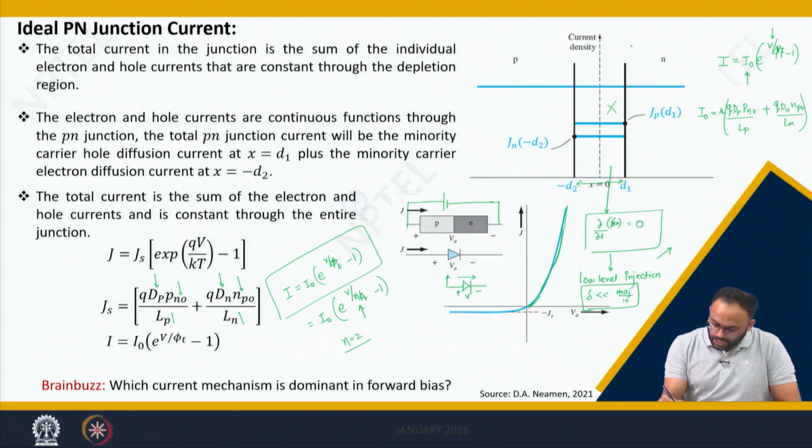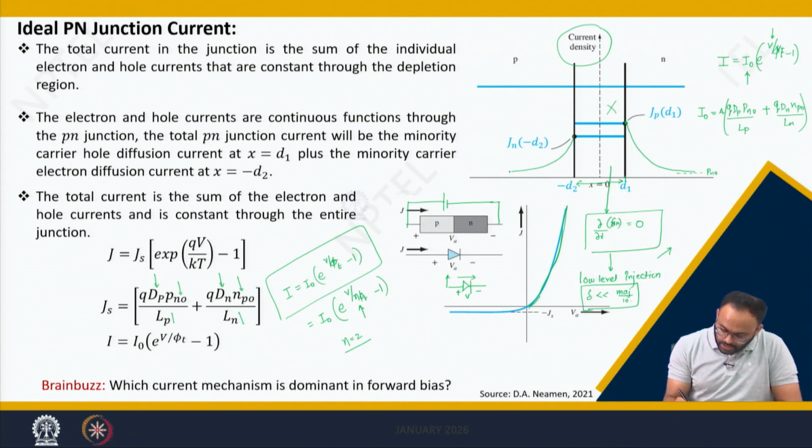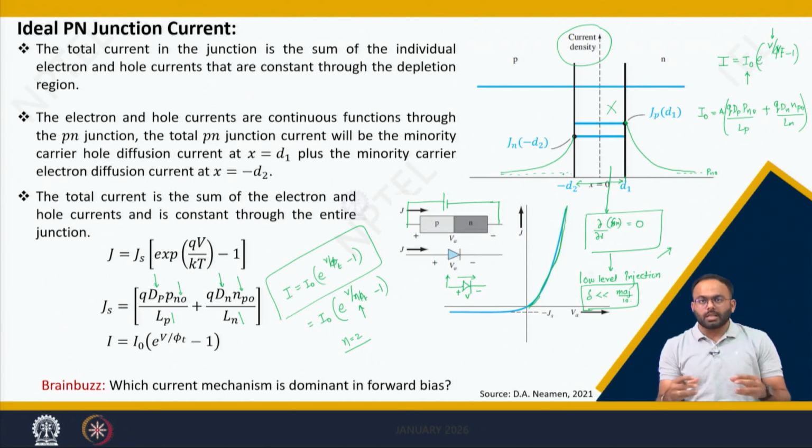Lastly, if you see this graph, which shows the current density, this point shows the hole current density at this junction. Now the holes will come here and ultimately they will diffuse. So this is Pn0. Similarly, these are the electron current densities and they will diffuse. But in the p-n junction there is not only diffusion current; there are also some drift components. How can we calculate?